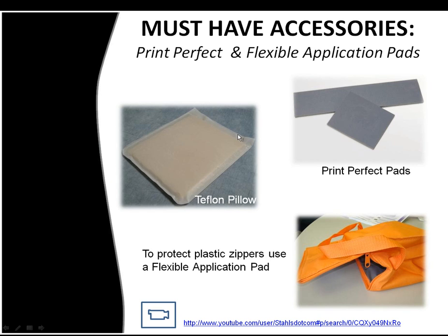Okay. Print perfect pads and flexible application pads and Teflon pillows. There are all different kinds of reasons why you would use one versus the other, and we've talked about this a variety of times, but print perfect pads and Teflon pillows are always available, and these help you with pressure. Whenever you need to heat apply onto something that has a button, a seam, a zipper, anything that's going to throw off your pressure, you're going to want to use a Teflon pillow or a print